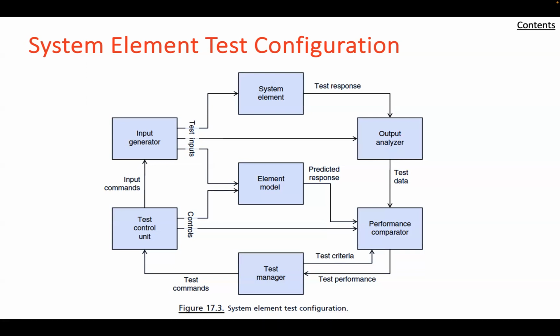For changes, if the diagnosis of a faulty test traces the problem to a component design feature, it is necessary to undertake a highly expedited effort to determine the most practical and effective means of resolving the problem. At this stage of development, the design should be under strict configuration management. Since any significant change will be costly and potentially disruptive, all means of avoiding or minimizing the change must be explored and several alternatives examined.